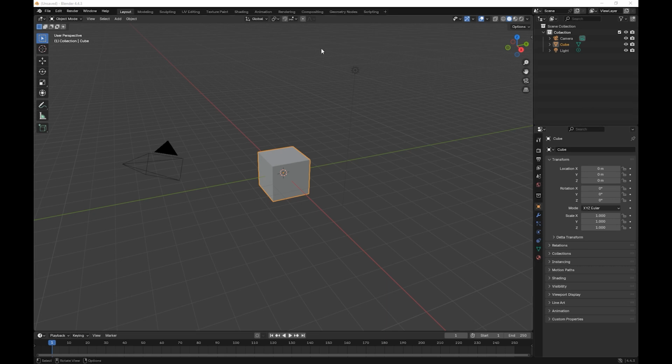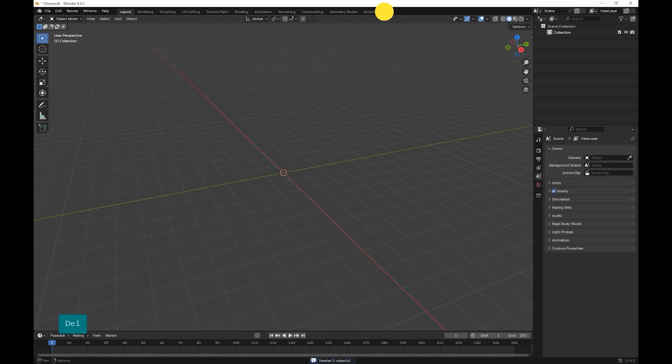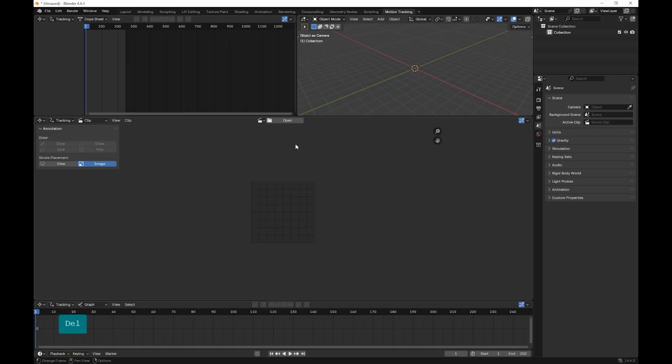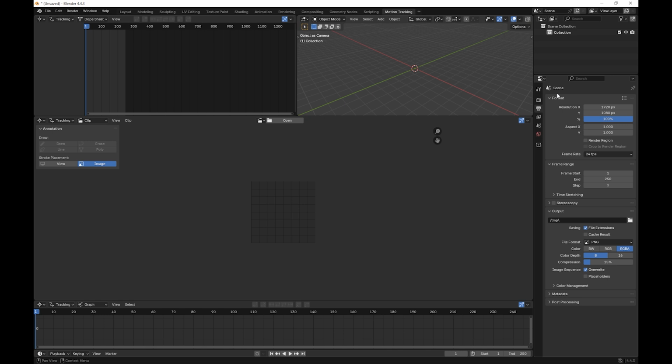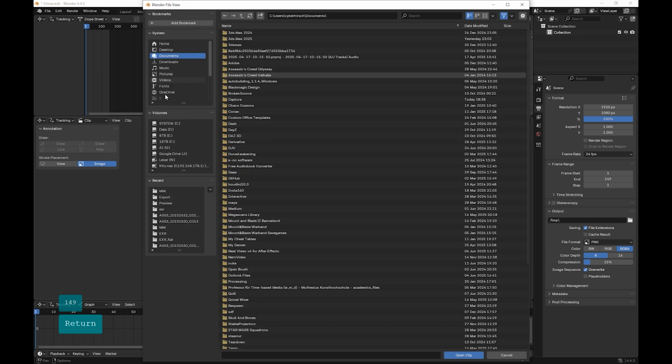Okay, let's get started with Matchmoving. First of all, you're going to go to VFX, then motion tracking. Be sure that your settings are correct and the output. The resolution has to be that of your footage, and the frame rate has to match your footage. We're using single files. I made proxies in JPEG format.